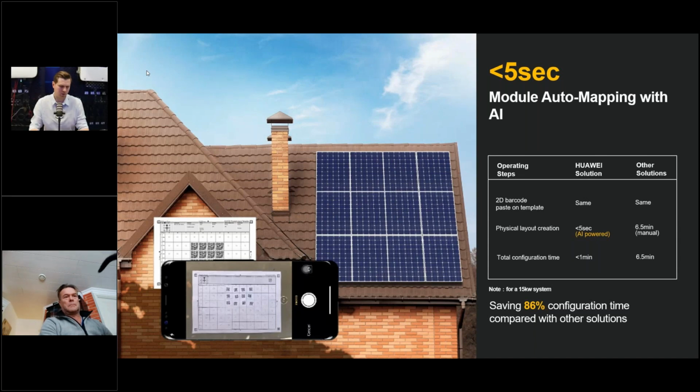I personally prefer not to add the PV modules manually, because those stickers work perfectly when we are in a controlled area, but when we have to move on the rooftop, in winter time, it's not a very comfortable way to unbind them from optimizers and put them on some template. It's just better to remember where we put those optimizers or write it down and make the physical layout peacefully afterwards, remotely from our office in FusionSolar.